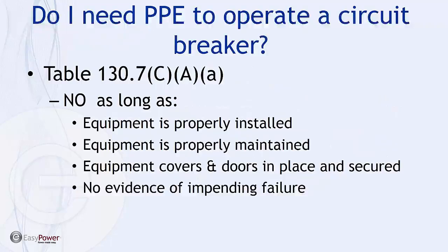Do I need PPE to operate a circuit breaker? According to Table 130.7(C)(a), no, as long as the equipment's properly installed, properly maintained, equipment covers and doors are in place and secured, and there's no evidence of impending failure.